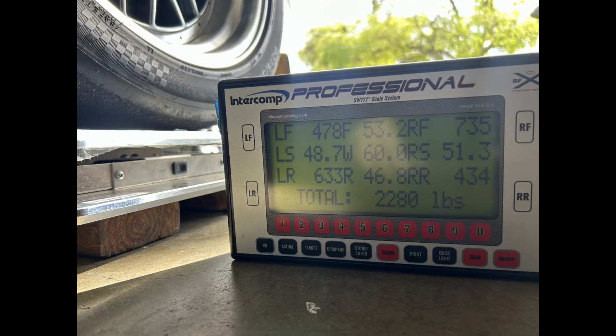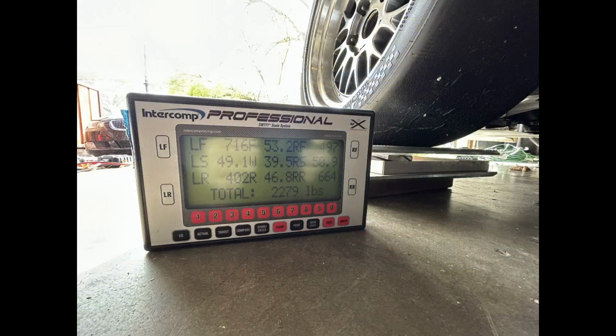This mode of suspension deflection is similar to warp, where diagonally opposed wheels move apart. I do this at each corner of the car, and the result is a data set of static floor offsets and corresponding weight transfers. To have any confidence in HyperMu's abilities, its predictions should be reasonably close to these data.